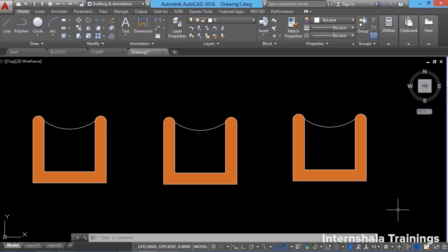This clearly indicates the fact that you can insert any other drawing into your drawing. But to create that external drawing, you don't have to actually go through all these procedures of making a local block, and then using the wblock command to create the external drawing. This procedure is not always necessary. Whenever you want to make a block that is to be inserted in all the drawings, you can straight away make that drawing. Then we will save it in a proper name and in a proper location. And later on, using the browse option of the insert command, you can insert it in any other drawing.